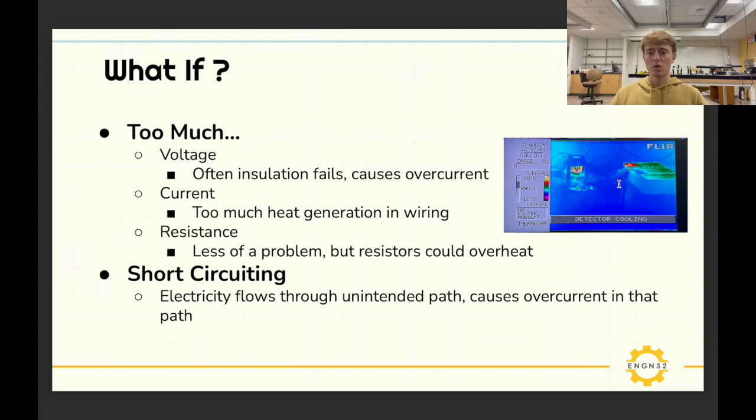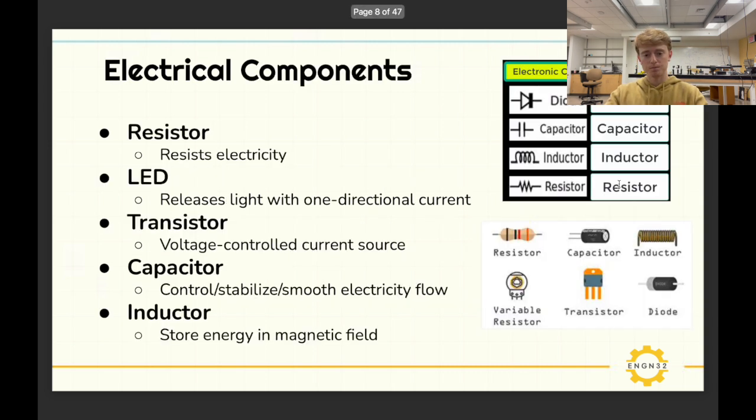So these are things we want to avoid. We want to really make sure that when we're soldering things or making connections, we don't have connections between areas that we don't expect. So you want to double check things, because otherwise you can have too much current flowing through something and you can blow something up, or just heat it up way more than you expect. A lot of times these mistakes are catastrophic and they blow parts. So just be aware of that.